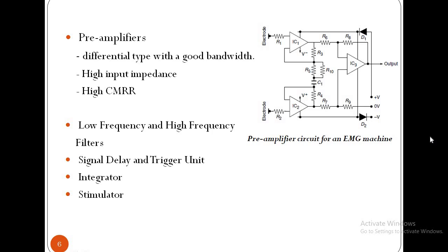This point is then considered as a reference signal and its signal is used to trigger the sweep. Signals from the remaining 13 points are then scanned sequentially and recorded with respect to the reference signal. To examine the signals, it is necessary to trigger the sweep from the signal and to delay the signal so that the whole of its leading edge is displayed.